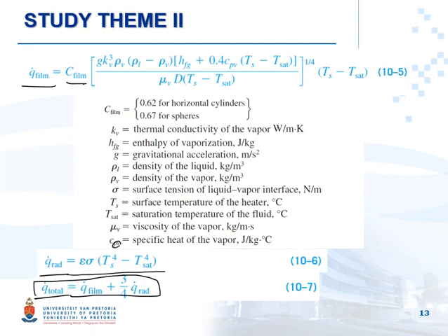Here you see that you have liquid and you have vapor. When I want to read the density of liquid, at what temperature should I read it, because let's say T sat is 100 and T surface is 800? They are very far from each other. At what temperature should I read? How about the density of vapor?